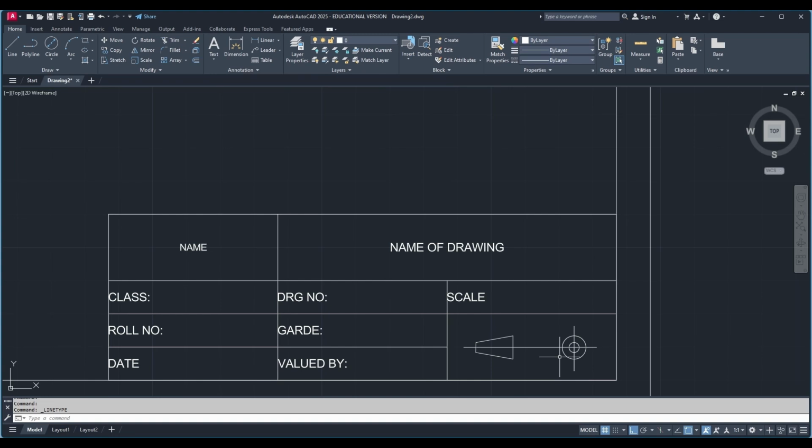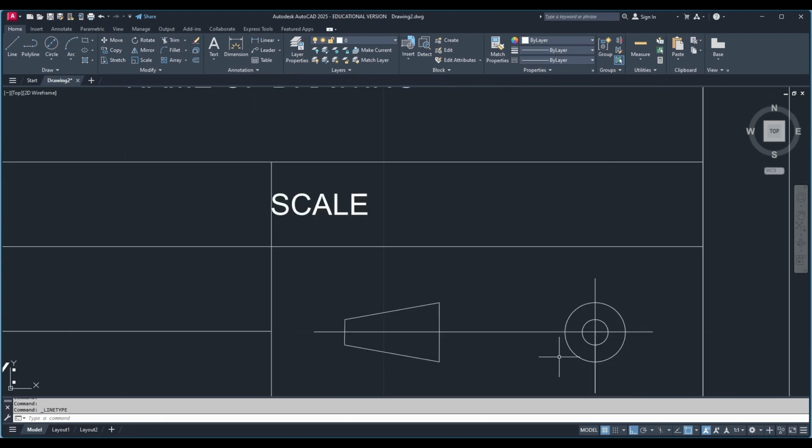Now you see here, even though you have selected the center line, you cannot see it. For that you need to click on line type scale factor LTS. Okay, so scale factor is 1. Here I am going to reduce it to 0.6. Okay, so still you cannot see. I think you need to delete it now. I'm going to delete it and we'll try redrawing one more time after selecting that line.